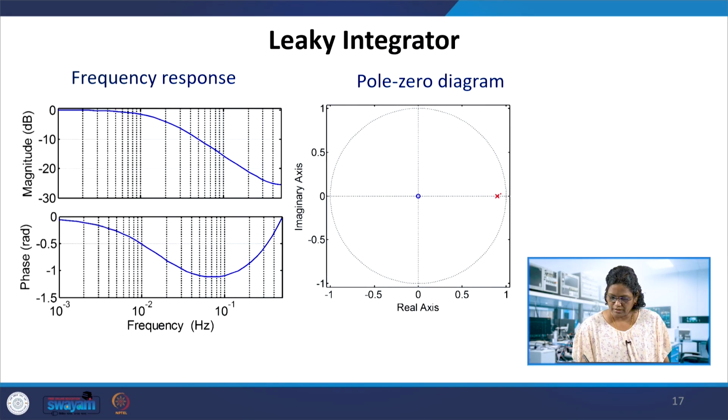The integrator has a pole which is not on the unit circle, it is slightly pushed inside the unit circle. So, here you can see the 1 is at 0.9 instead of 1. In the case of the slope, if you take this leaky integrator, it is a straight one, and we have a small change in the smoothness of the integrator.